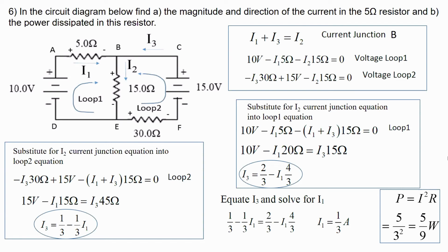Yeah, because that's the current that's flowing through that particular resistor. We could have picked, for example, the middle resistor, and then we would use I2, but we would have to calculate I2 first, or the voltage. Right. Okay. Yeah, I think I got it. Okay. Any other questions?